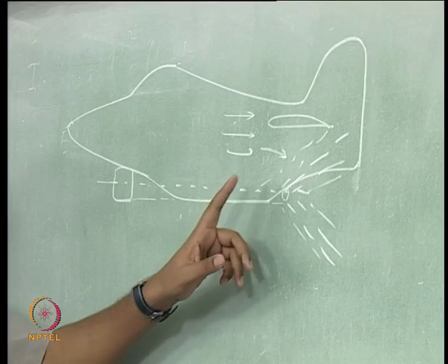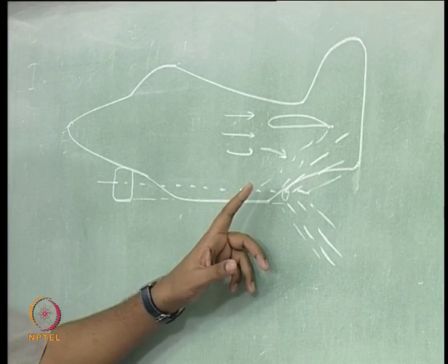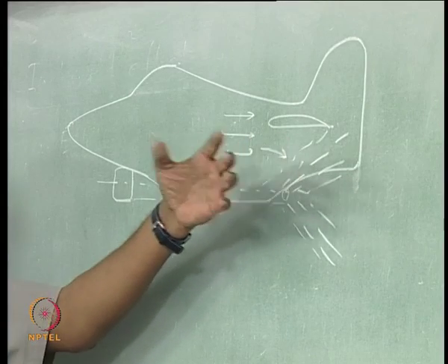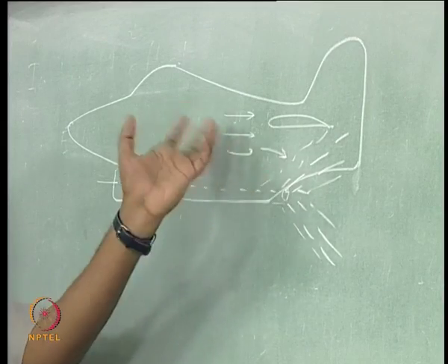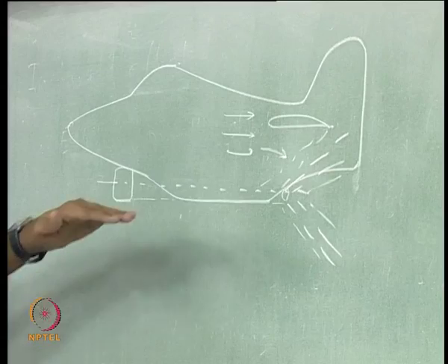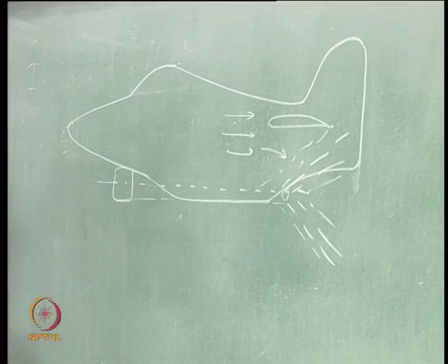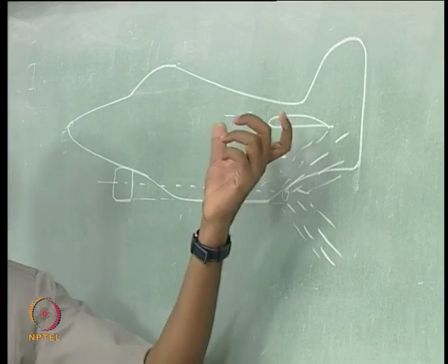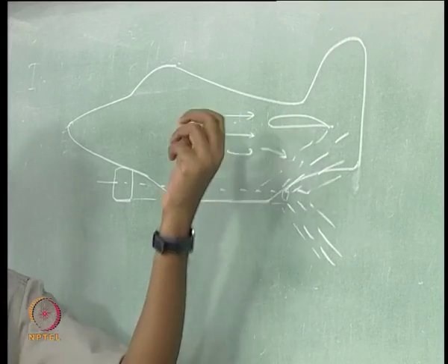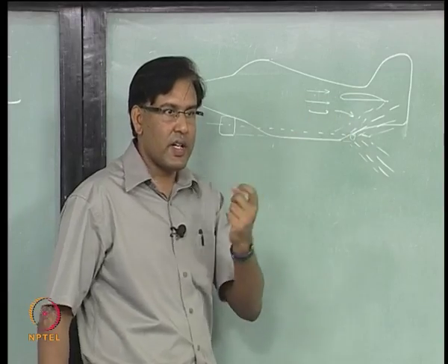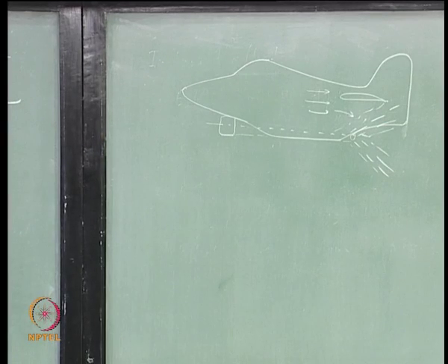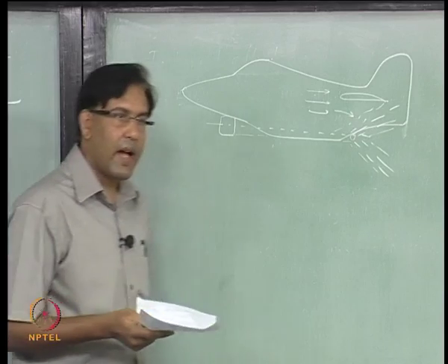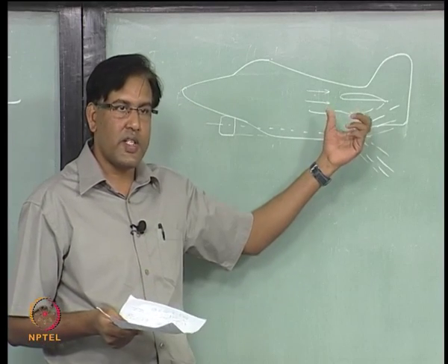Why is that? This jet is coming at high speed, right. So, there will be a drop of pressure and then it starts pulling the flow which is going over the tail, is it not. So, there are two effects actually which it can have on the tail itself. One is the tail is going to see a drop in relative wind speed, right, and also the angle of attack at the tail is going to change because of this, right.